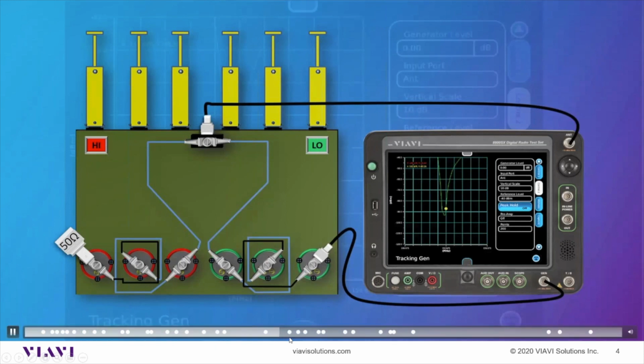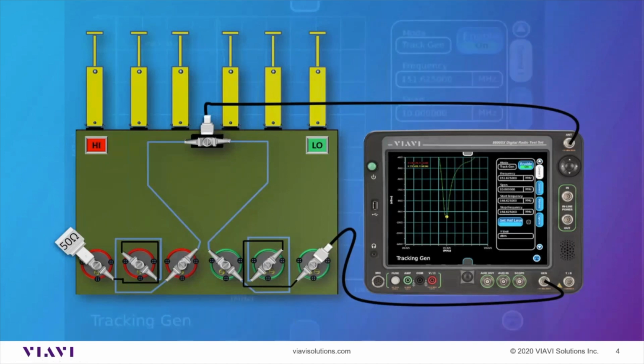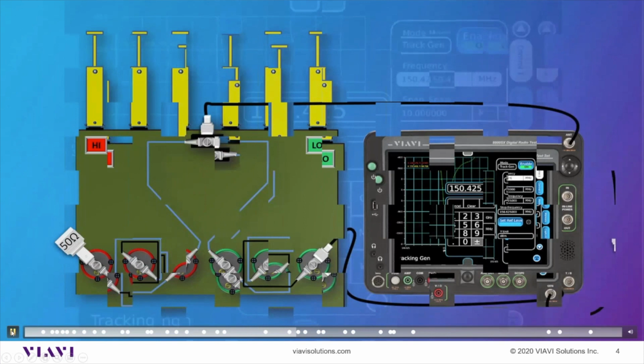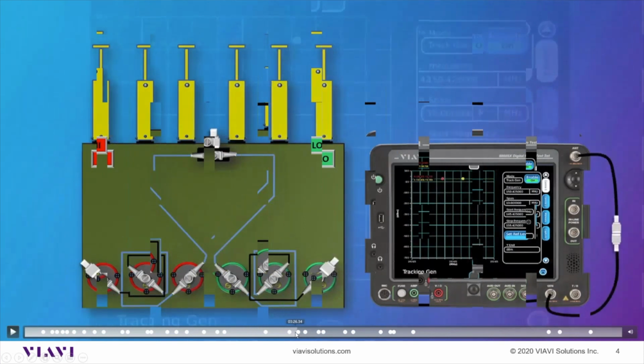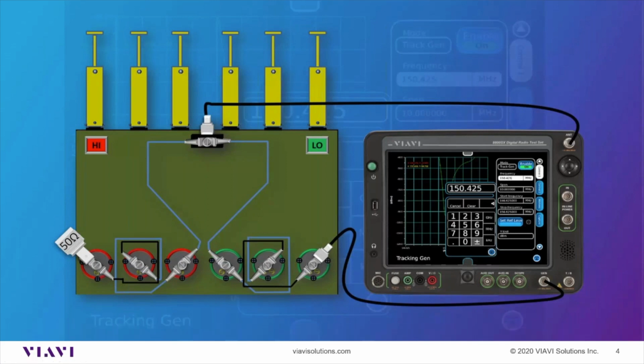So we're just moving along and optimizing that as best we can. Like I said, we haven't done any set references at this point. I'm just trying to get everything on frequency, and then we'll go back. And by the way, let me back up just a bit there. I've got this adjusted about where I think my optimum adjustment is. And so what I'm going to do here is set the center frequency in between the high pass and low pass.